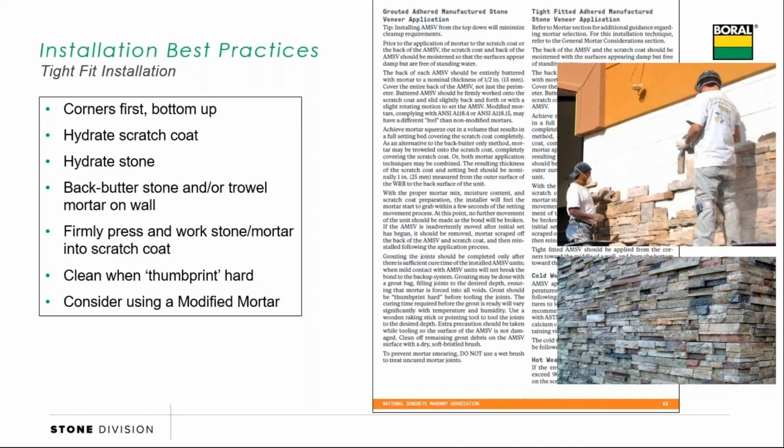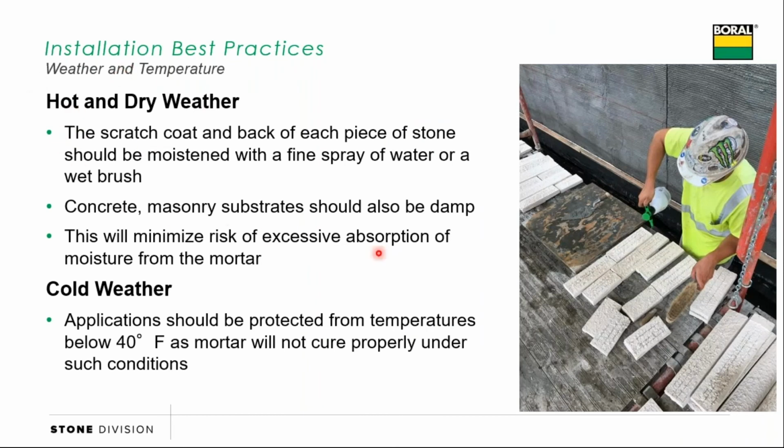So please, in any hot weather or dry weather, hydrate the scratch coat, hydrate the stone. You can use a garden mister, a bug sprayer. You don't want to see water pooling on the surface, but as long as it's hydrated, now that mortar has a chance to dry at a normal rate. It's kind of like concrete. The slower a concrete dries, the harder it is.